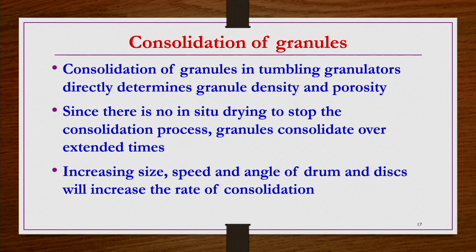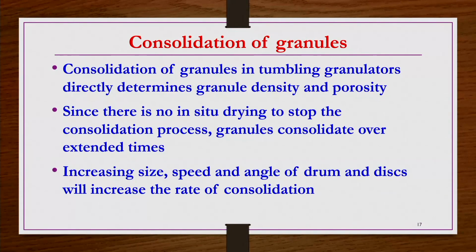Similarly for speed, if you go more than 50% of the critical speed, then again consolidation may be a severe problem. And the angle of the drum also cannot be large; it should be up to 10 degrees from the horizontal, otherwise consolidation will increase.